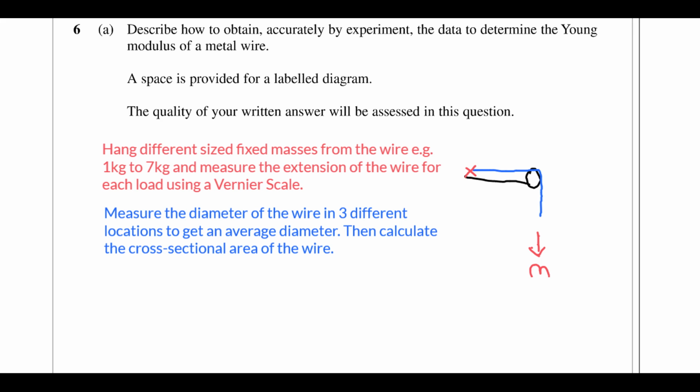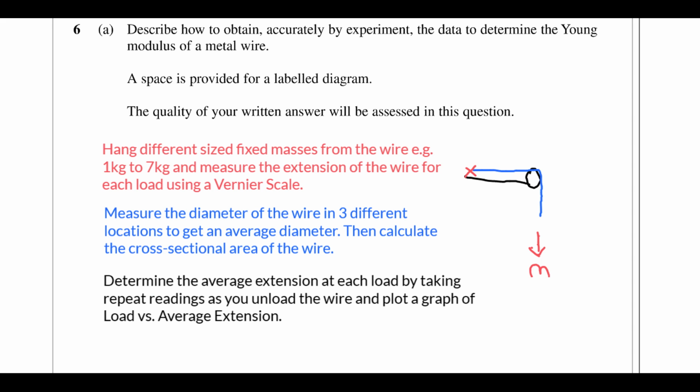So let's look at how we're going to get the graph that we need. To ensure our readings are as accurate as possible, we're going to take repeat readings of extension and get an average extension for each load, and we want a graph of load versus extension.